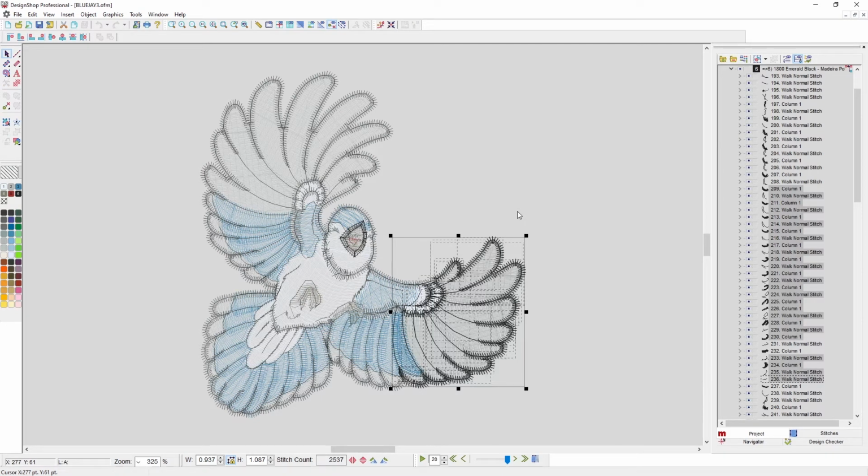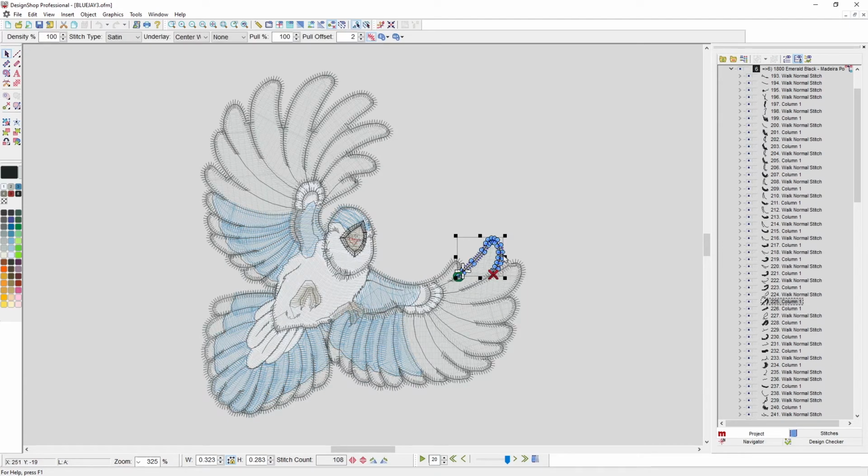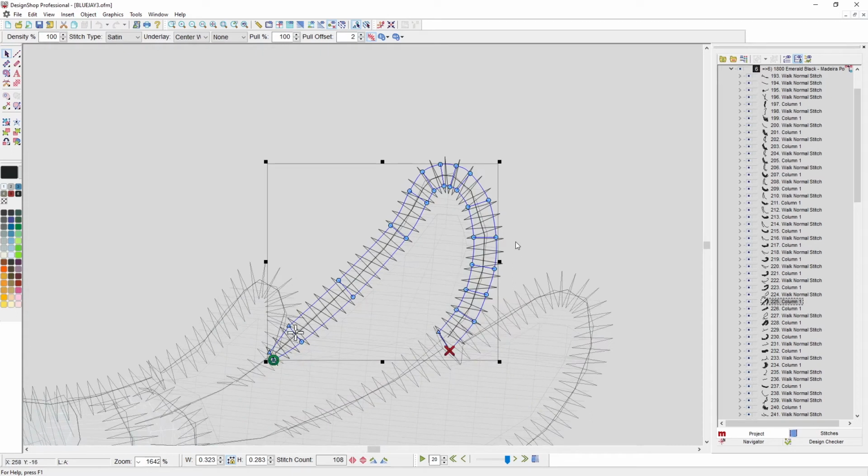Now, it says custom point selection tool. Obviously, just now, I wasn't dealing with points. I'm dealing with entire elements. But it can work with points. So if I have an element selected and I'm going to zoom in, I can use the custom point selection tool to select certain wireframe points. I can do the same thing with stitches if I'm dealing with expanded stitch editing.